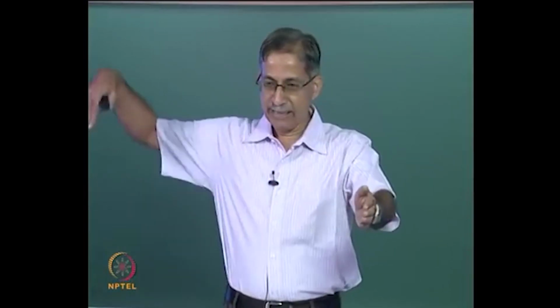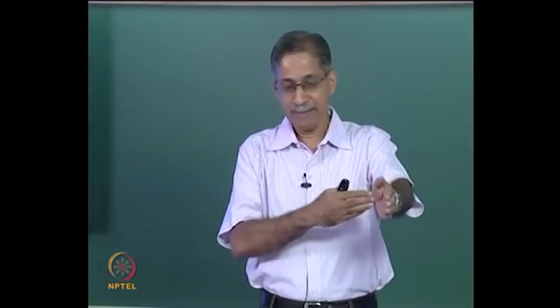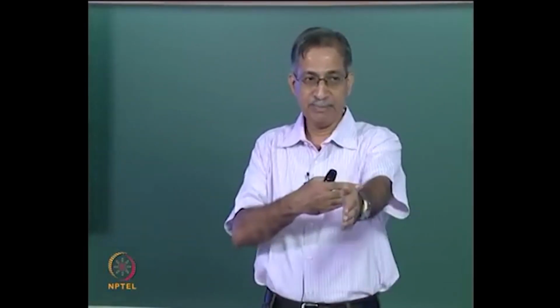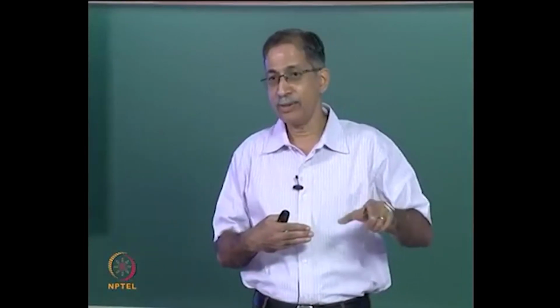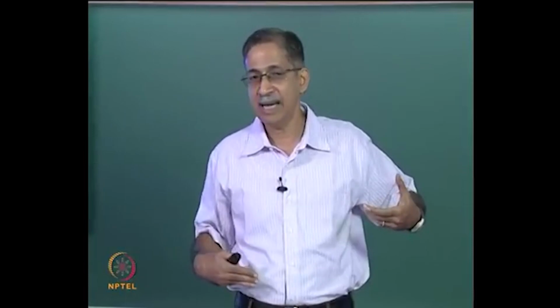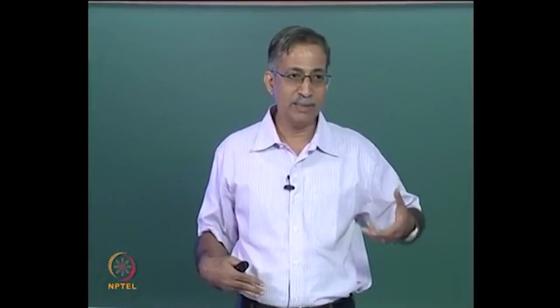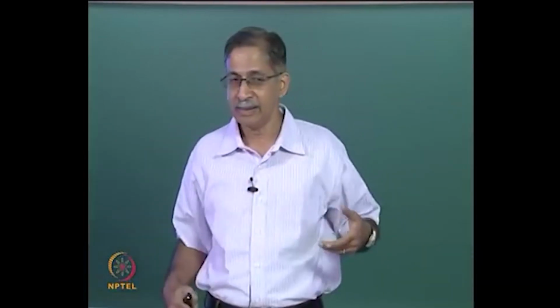When this beam bends, it is going to have a flexural rotation at this end, and because it is integrally connected to this beam, that beam is also going to rotate. But what is a flexural rotation for one beam is an angle of twist for the other beam, and how much moment is transmitted at that junction depends on the torsional stiffness of this connecting beam in addition to the flexural stiffness of this beam.